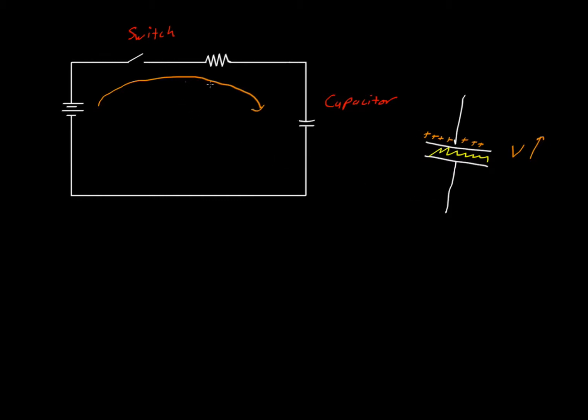After that happens, current flow stops. Whenever we reopen the switch, however, all this stored charge is going to discharge and it's going to equalize back. It's going to push back, it's going to discharge, and it's going to pull negative particles back from the negative side to equalize this voltage and cause this voltage to go down on the negative side. Okay? So you can think of it almost like a short-term battery.